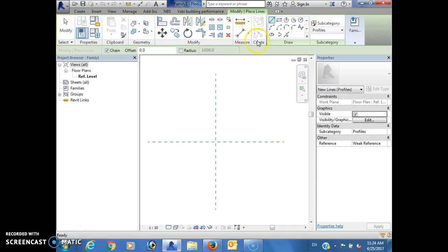So for the coping, I'm going to draw, for example, a coping where our parapet is only 10 centi. Let's say 2 centi of plaster each side. So 2 and 2, and I want 1/2 a centi more, so 15 centi, and the height 10 centi only. This is a very small coping. This one, I want a 15.